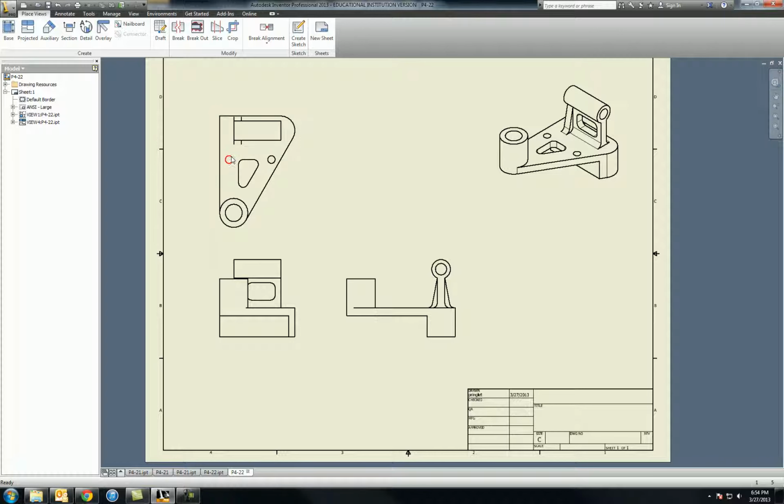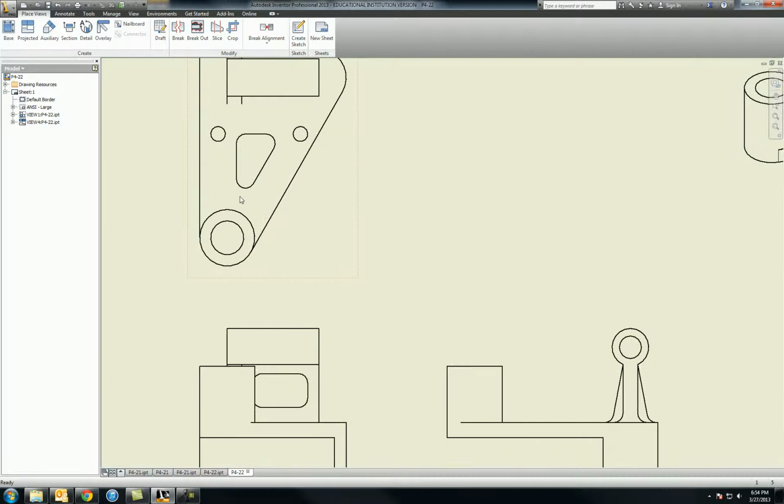The other thing is the location for these two holes. While they're given a location from here down, this hole is not technically dimensioned the way that it needs to be dimensioned, because a lot of the things that are going on in this particular drawing don't make any sense. For example, having this dimensioned out here to a point, that's not going to happen. Nobody's ever going to do that. That's only done in the textbook to make it easier for you to draw, but that's not how it needs to be dimensioned for the purposes of what we're doing, and I'll explain some better ways to dimension that.